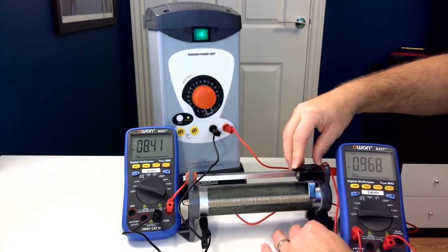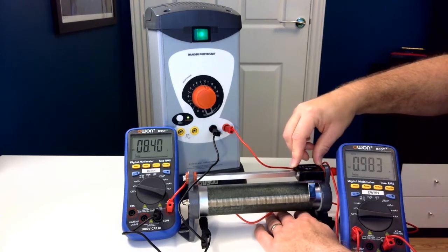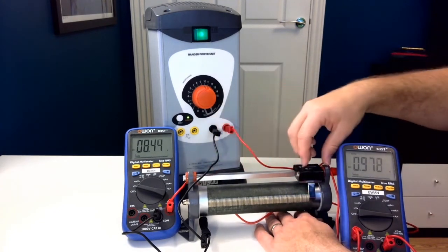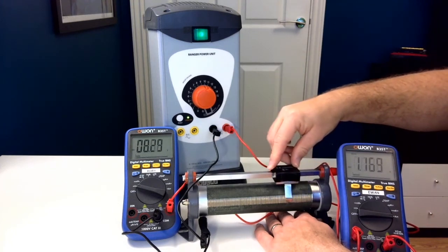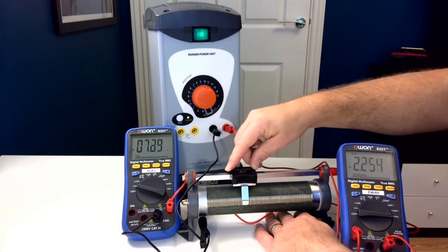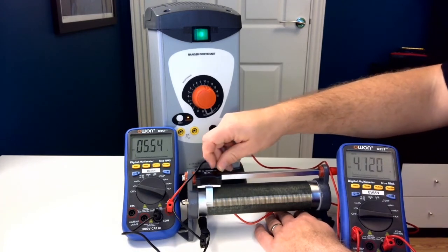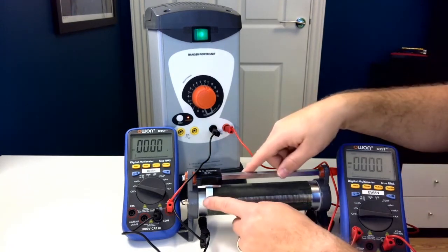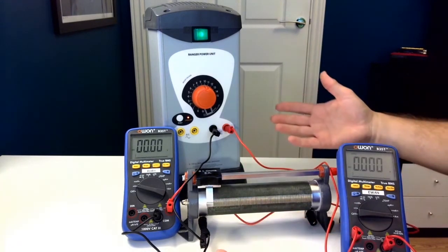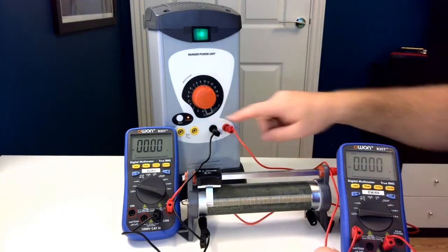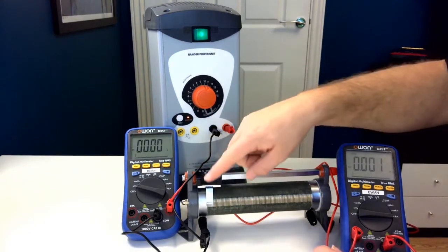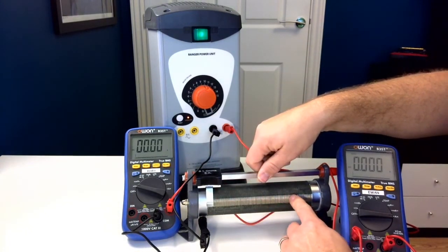What they will do is they'll want to take 6 readings, and they'll go 6 readings all the way from here all the way across to there. So 1, 2, 3, 4, 5, 6 readings. Now we have 2 problems with that if we do it. First of all, when we get down to here, everything stops. And that's because we've had an overload of the circuit. Effectively, we've short-circuited because we've set the load resistance to 0.